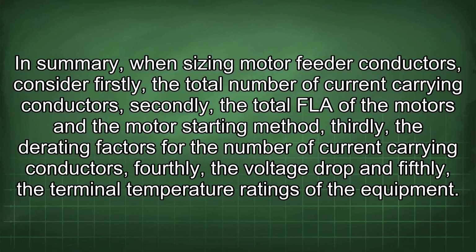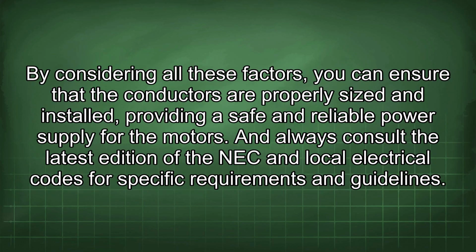In summary, when sizing motor feeder conductors, consider firstly the total number of current carrying conductors, secondly the total FLA of the motors and the motor starting method, thirdly the derating factors for the number of current carrying conductors, fourthly the voltage drop, and fifthly the terminal temperature ratings of the equipment. By considering all these factors, you can ensure that the conductors are properly sized and installed, providing a safe and reliable power supply for the motors. And always consult the latest edition of the NEC and local electrical codes for specific requirements and guidelines.